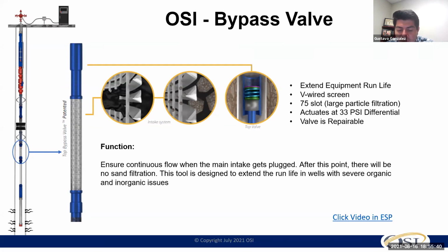I was going to give an example. There was one well that we did a couple of weeks ago that we were expecting 120 pounds of sand at the surface, and this well came back and the bottom hole pressure increased, total fluid production actually went up like 40% more, and now the sand rate of course increased, and now we're facing 288 pounds of sand at the surface. So imagine how much sand is passing through the ESP.